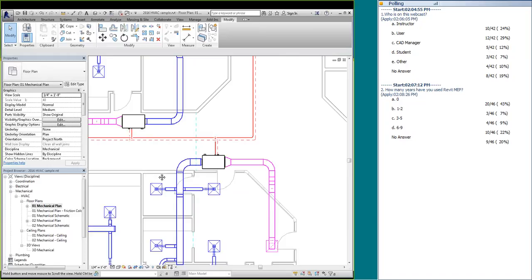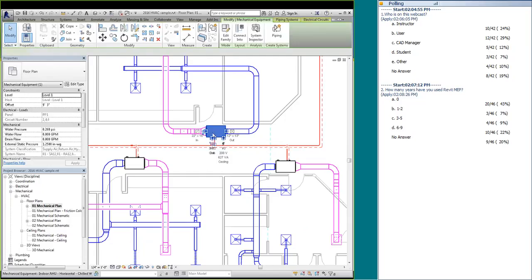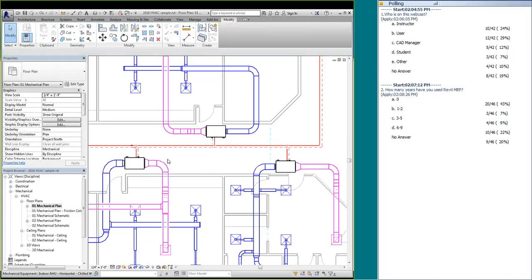Another little thing we did that just saved a bit of time, and you're still learning everything you need to: when we have the students insert the mechanical AHUs, air handling units, we make sure that all of the piping, you can see the piping right there, is facing out to the hall. Before, you had to take that piping around and under, making sure you weren't hitting the ductwork. This is a much more elegant solution, so it'll be easier to draw in the first place, but also a little bit more real world from what you would actually have.